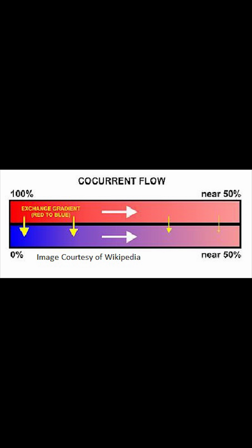This heat transfer process is actually similar to what you might see in a co-current heat exchanger, as is shown here. Both the hot and the cold stream are traveling in the same direction. This type of heat exchange doesn't always make for the most efficient system, but works well for a hot water heater because no pump is needed to make the flow of water move. Density gradients and gravity take care of that for you.